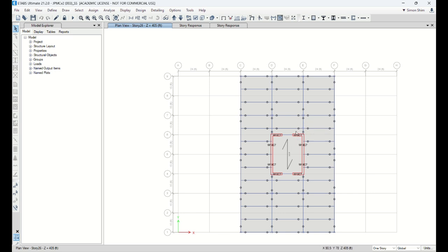It's not that big a difference, but somehow you will see that wind blowing in x direction has a more tributary width, 1, 2, 3, 4, 5, 6, 7, 8, 8 times 15, versus wind blowing in y, where the tributary width is 72. So you could see the wind pressure demand and the stiffness of the concrete core wall slightly change along the height.